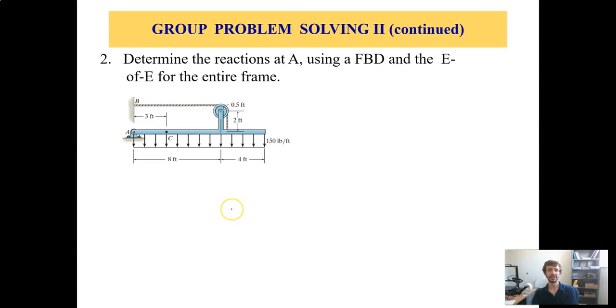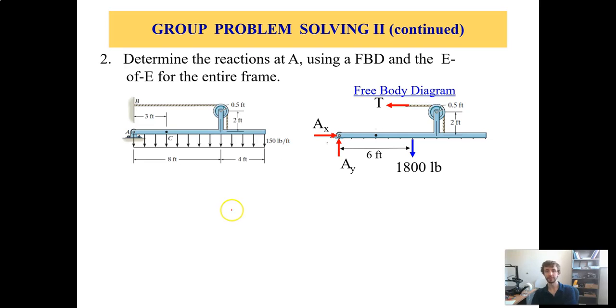So first off, we're going to need the reaction forces. So how are we going to find that? Well, first we actually got to draw a free body diagram. And wait a second, what happened to our point B? Why no reaction force right here at point B? Well, we could have had that, and that would have been completely fine, but it makes a lot more sense just to cut the rope. Cut the rope, and suddenly, wait a second, this looks a lot like our previous problem.